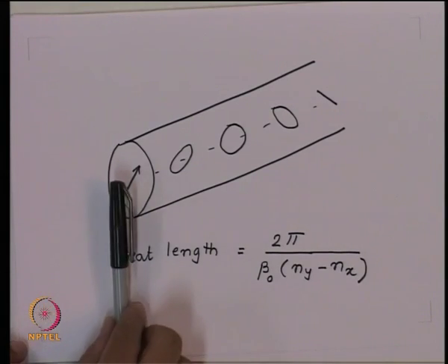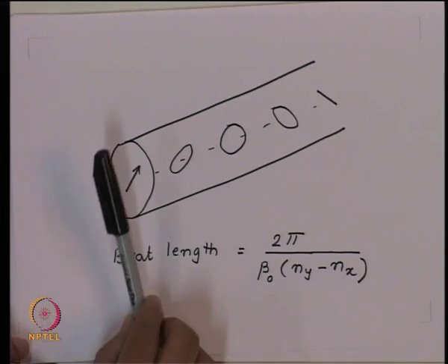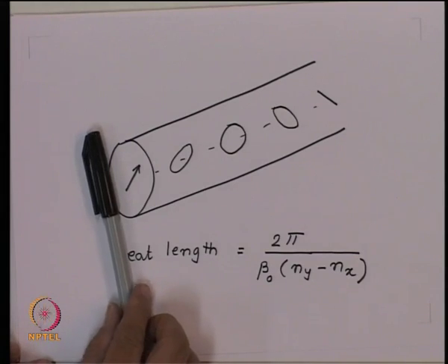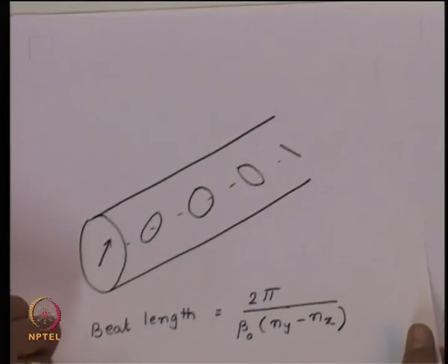If I see in terms of the group velocity, the same thing will happen to group velocity also, that whatever pulse I launched inside this, the pulse energy will get divided into two polarizations, horizontal and vertical, and the two will travel with different group velocities. So, you will see that there is a tendency for the pulse to separate out because of this.